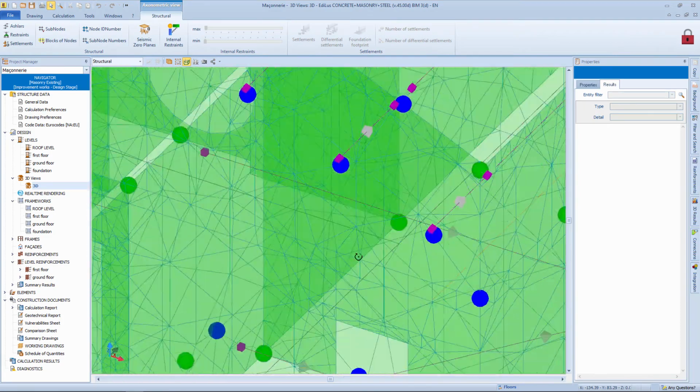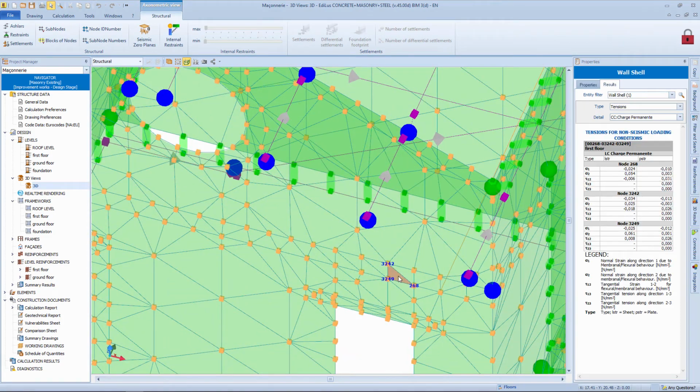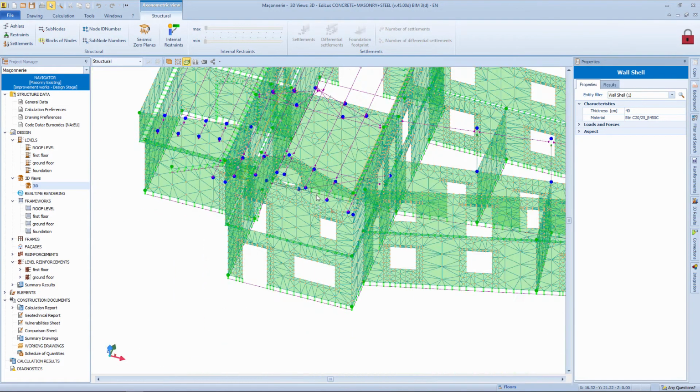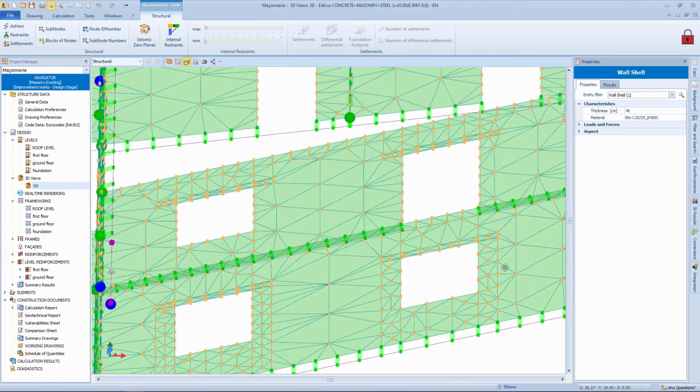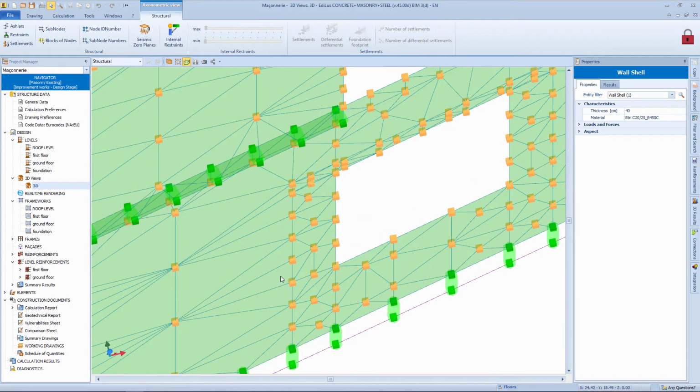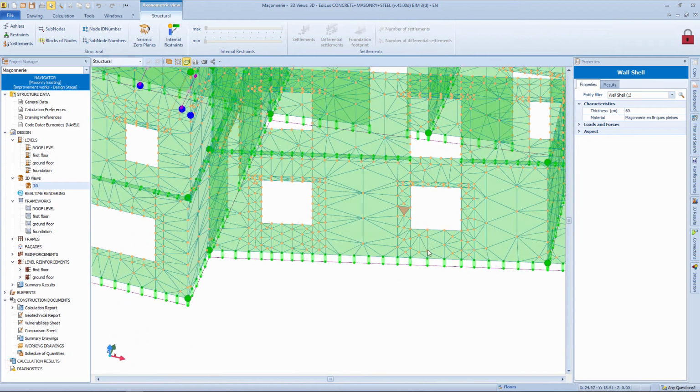If we consider the structural model at the shell elements in which the chain is located, we see a reinforced concrete element. So this model allows us to differentiate the types of materials in a quick and local way. Same as if we go to the 3D views and see a window in the shell environment, the elements near the opening are characterized by different materials. So this shell view allows us to have a local characterization of the materials.